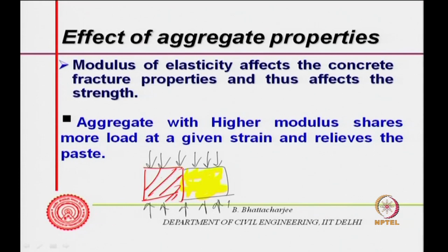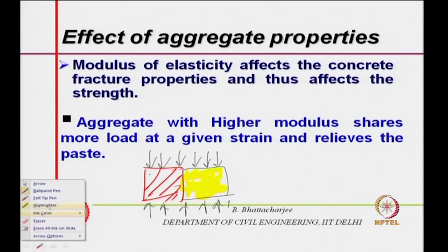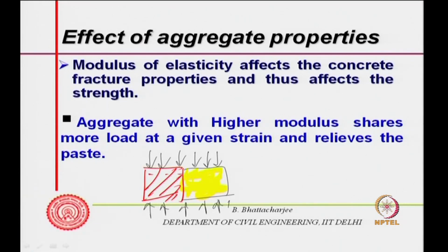So, under the same deformation, the deformation is the same. This one has a low E, and this one has a higher E: E aggregate is higher than E paste. So, with E aggregate higher, it will actually take more stress, depending of course on the proportions.